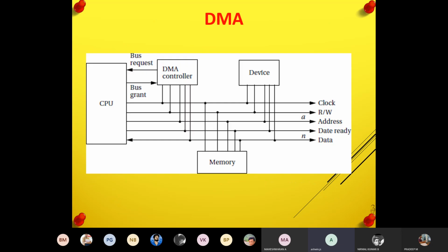Direct memory access. I will tell what direct memory access is. We may have only 20 minutes remaining. Direct memory access is used to access the memory from the input output devices without any interference from the CPU, so that I am able to do things simultaneously. The CPU will work separately, and similarly if the input output device wants to access the memory, or read from the memory, I will use the DMA in order to control it.